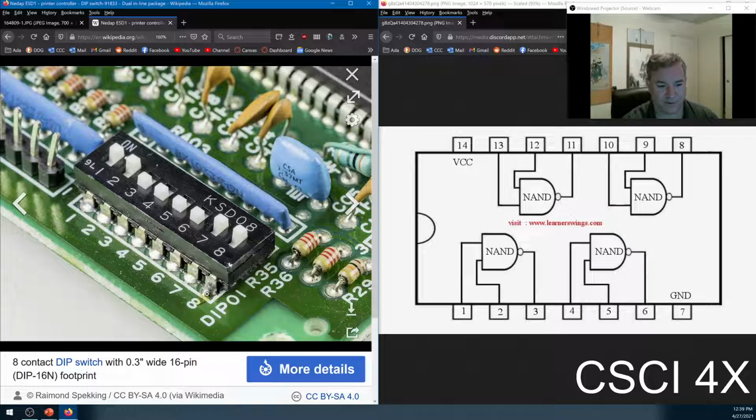And so the solder kind of sticks. It's at high temperatures, like 300 degrees or something like that. It's molten, and then when it cools, it solidifies. And so solder, if you heat it up with a heat gun, let's say you want to take this resistor off, you would apply heat to it. The solder would look solid, then it suddenly turns into a bead of metal.